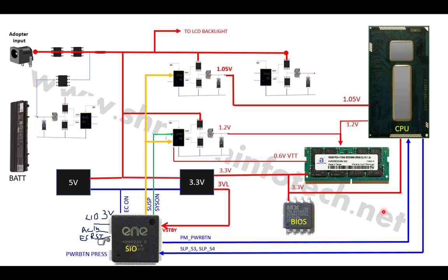So in total, there are 4 voltages given to the RAM on DDR4 sections, or DDR4 RAM. Okay, so now most of our components, or most of our chips, are turned on. Only one chip is still not turned on, and that is the CPU. Now the CPU requires a core voltage.